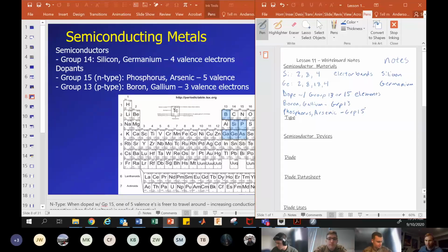We don't want to get these on our hands or ingest them. So don't eat any of the integrated circuits that I pass out to you. Well, as far as I know, they're perfectly safe to handle. Although that does remind me, especially living in Colorado, static electricity can break electronics. So when we are in the lab and we're handling these things, especially if the air gets really dry here in the winter, it's easy to build up static electric charge. You can probably zap your roommate and stuff. You want to discharge yourself, meaning touch something metallic to ground yourself, before you handle any of these little microcontrollers or integrated circuits that we're going to work with.